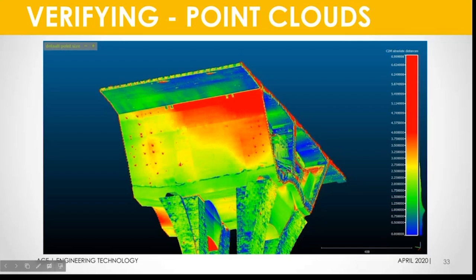Now, mind you, it may only be fractions of an inch, but in some projects, you can have very tight tolerances where fractions of an inch really add up and matter. So in this case, to verify that this really large structure was still within the allowable tolerances, we went out and laser scanned it and compared it to the model. What you see here is the varying colors representing how far from the design certain areas are. So we could very quickly verify that all of the formwork and everything was moving and setting just the exact way that the computers predicted that it would.